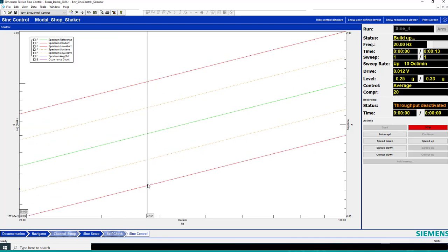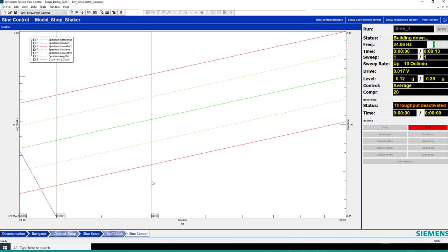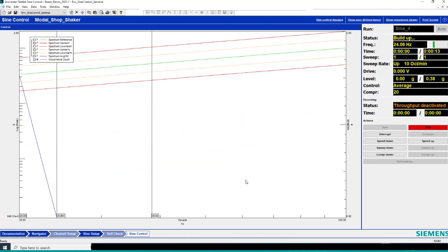This is my resonance frequency, somewhere around here, around 40 hertz or so. So you can see immediately with those setup parameters, I am aborting. I'm way outside these minimum abort limits. So it's got an update to the transfer function at this frequency, at this occurrence count. So I am going to go ahead and resume and see what happens.